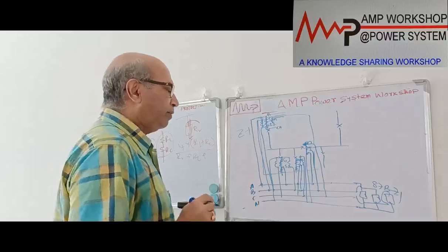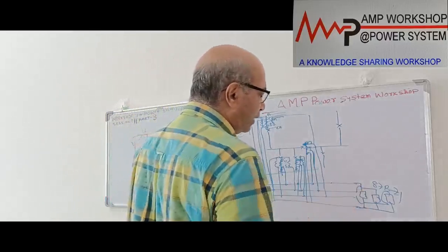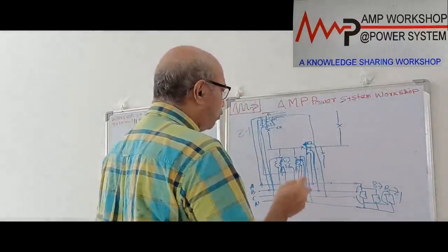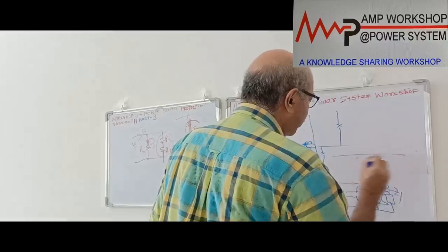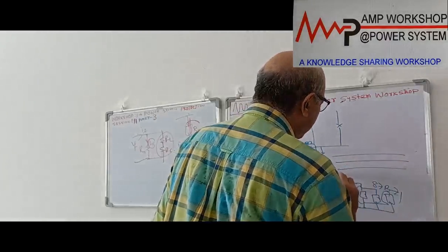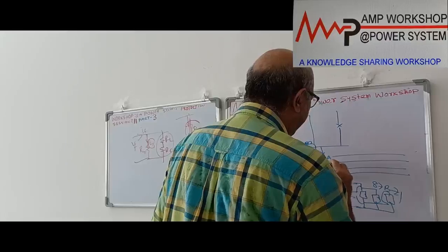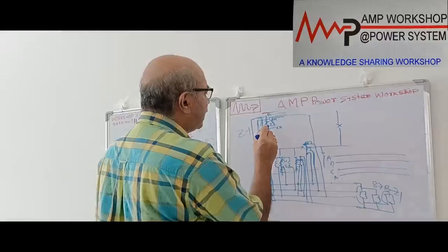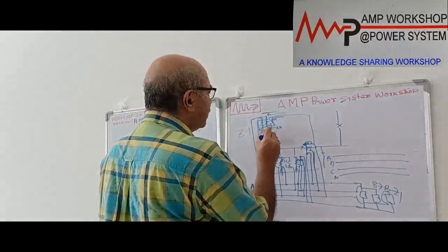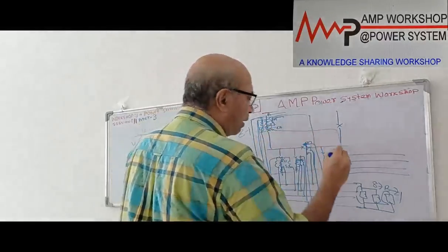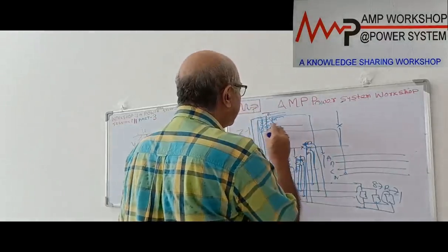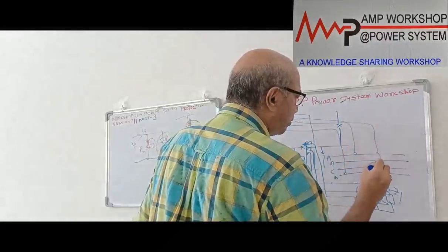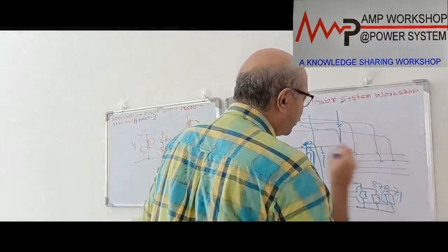Now here we have to do one thing. When we are connecting this relay from here, similarly this is one zone. Similarly, the second zone, the check relay, that also there will be ABC 3 section, ABCN. Here is the same way as we did for the other relay. Here also there will be 3 sets of CT. This is the neutral. The neutral will be coming to the N bus, and then this CT will be coming to the A phase, B phase will be connected to B phase, and C phase will be connected to C phase.